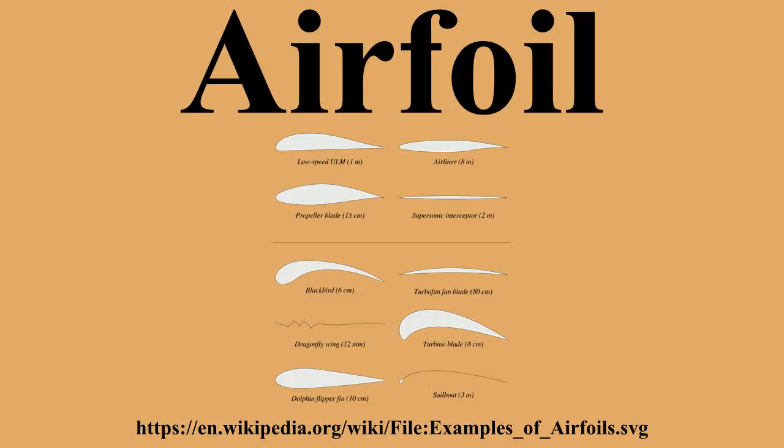An example of a general-purpose airfoil that finds wide application and predates the NACA system is the Clark Y. Today, airfoils can be designed for specific functions using inverse design programs such as PROFOIL, XFOIL and aerofoil. XFOIL is an online program created by Mark Drela that will design and analyze subsonic isolated airfoils.